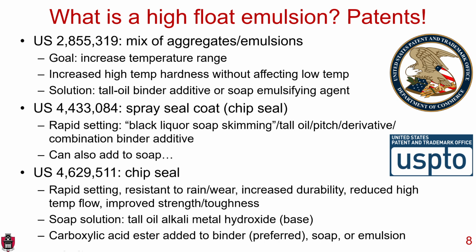And then finally, 4.6 million. This is just for a chip seal. This is explicitly rapid setting as well. And it's resistant to rain and wear. It has increased durability. It has reduced high temperature flow. Notice how they emphasize the high temperature. And then it provides improved strength and toughness.